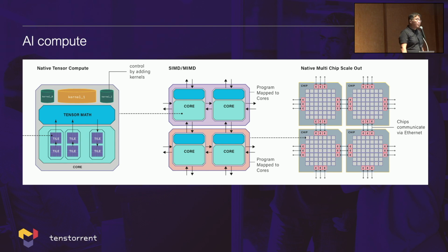You can see here, these are the Tenstorrent technologies that we're forming from the Tensix on the left-hand side. You can see there are 5 embedded RISC-V CPUs, very simple embedded RISC-V CPUs in there. You use that as a composable element to make a larger chip, right? In our example, we're using a 2D mesh, connecting them together and forming a chip. Then you can connect these chips together using our Ethernet scale technology, forming a chiplet, right?